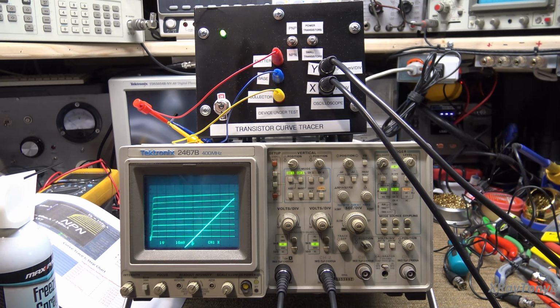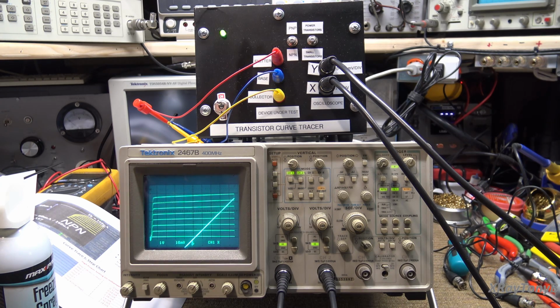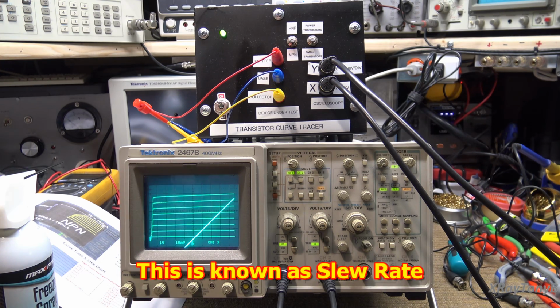Now, just like collector to emitter voltage can affect the gain, it's only slightly, you can see, but it does. The frequency of the signal that you're applying to the transistor will also do that. So as you go from DC up in frequency, as the frequency increases, the gain of the transistor decreases. And this has to do with the amount of time that it actually takes a transistor to go from one state to another, like from turning off to turning on, or turning on to turning off, or from changing from one voltage level to another.